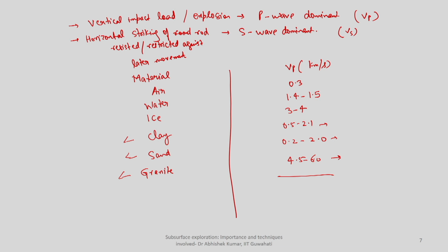You try to measure the physical properties of the medium, and depending upon the range of physical properties of different media, directly when you go for seismic methods, or indirectly when you go for other geophysical methods, you will be able to identify what kind of medium is there, what its physical properties are, and at times what the depth of the medium is. Again, each of these properties is related to the physical properties of the medium. So let us see how Vp, the primary wave velocity, can be related